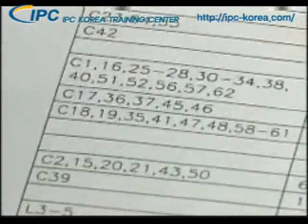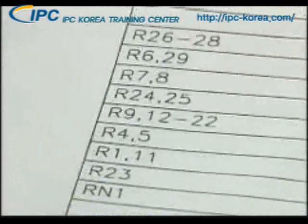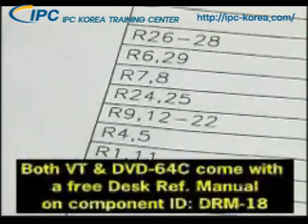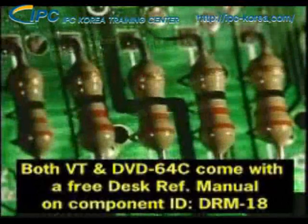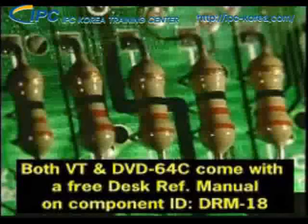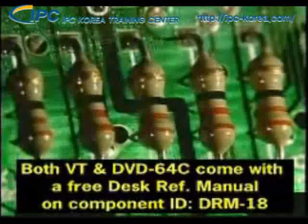There is a reference designator assigned to each component on the circuit board. For example, resistors utilize the letter R as a reference designator. If a circuit board contains 30 resistors, they are usually identified as R1 through R30, even if they are all the same part number or value.